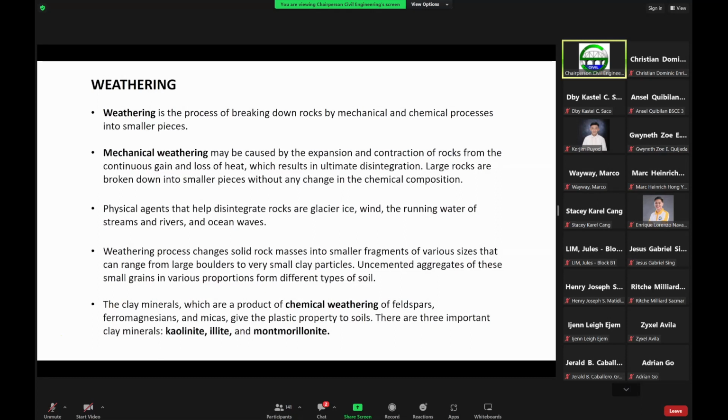So for example, if you have a 30-meter depth of borehole that you drill on site during the geotechnical investigation, and you do the sampling every 1.5 meters, then there will be about 20 samples in a depth of 30 meters, wherein we will have to describe each material.